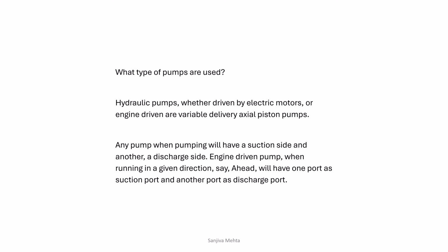Correct? But now the question arises, since these pumps are attached to the engine, what happens when the running direction of the engine is reversed? Let's say now running in the eastern direction. Don't you think the port of the hydraulic pump will also change? The side which was suction side will become a discharge side because the direction of rotation is reversed. Pump will be running in another direction, and the side which was the discharge side will become suction side.